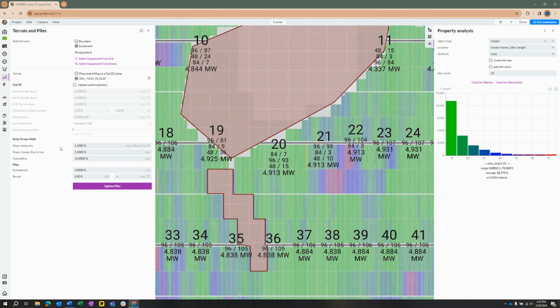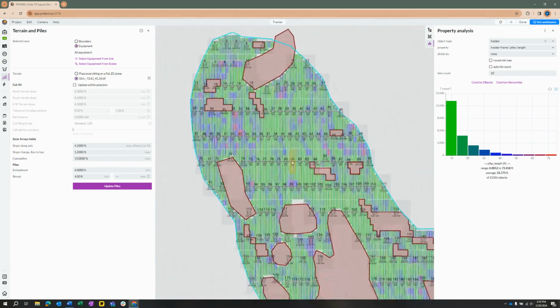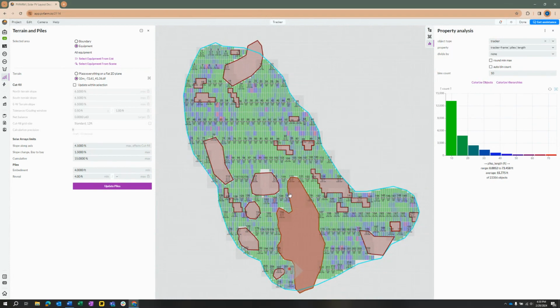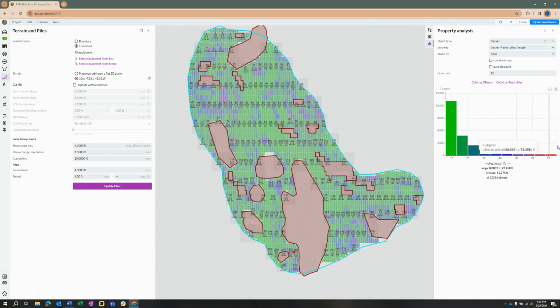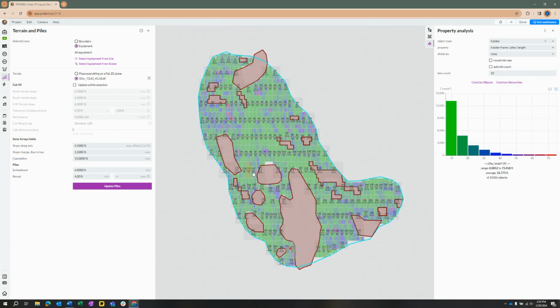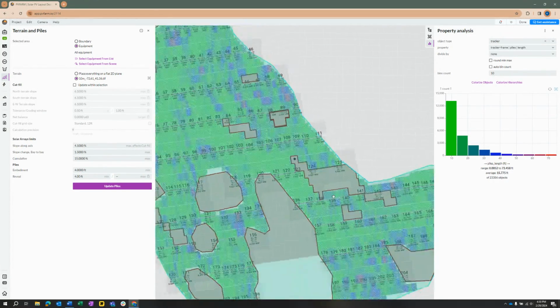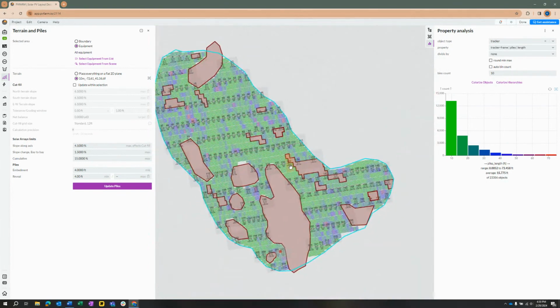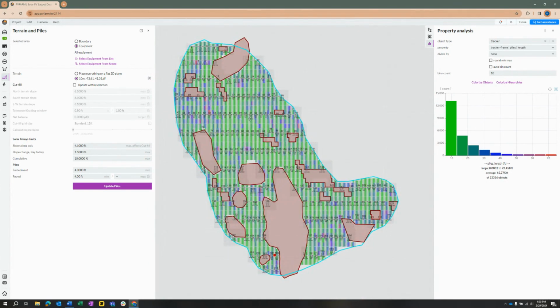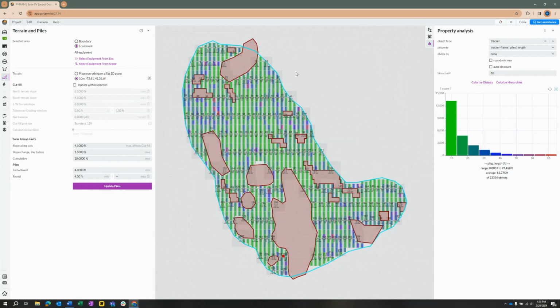Now, we've done this using 1.5 and 15%. This is going to vary depending on your manufacturer, how much of a percentage and how much of slope change you can do. We could also come here and change the slope along axis. And we can use these two techniques to work on shortening up these piles even more. We can come in and cut out more using the boundaries method. We can make more things terrain following trackers. This is depending on the slope until we're in a more reasonable range to begin cutting and filling.